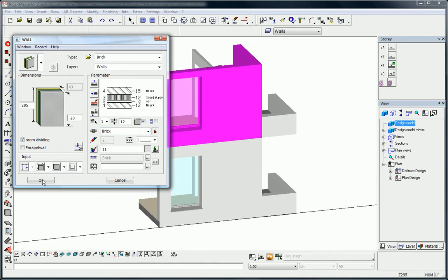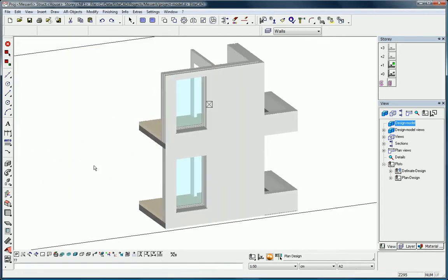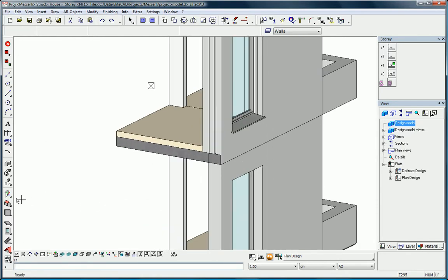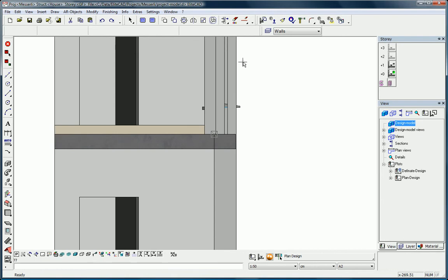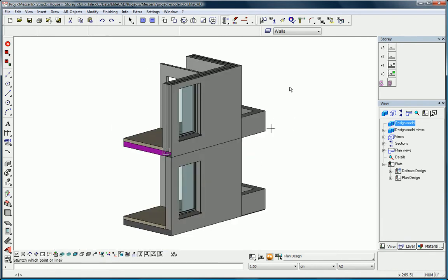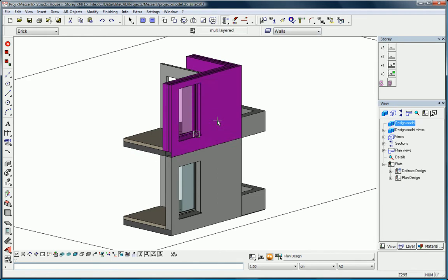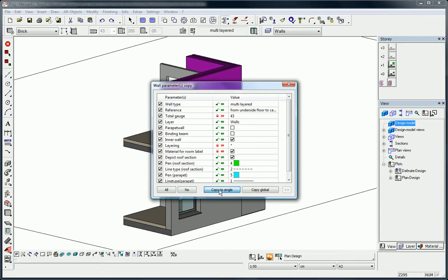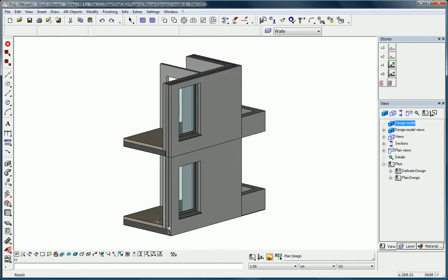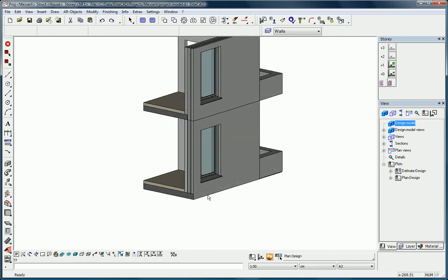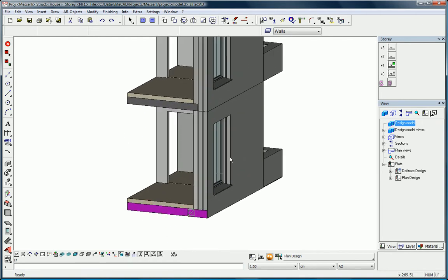Now we will customize the model. In this case, this means that we can distend the ceiling, which currently stands too far forward, and move it back onto the bearing frame. This adjustment can be made directly within the section, and of course also in the plan and elevation views as well. Now we will pass on the information of the multi-layered wall onto the floor below, and the new wall immediately inherits matching components. The ceiling here is also adjusted accordingly, in order to achieve a correctly constructed model.